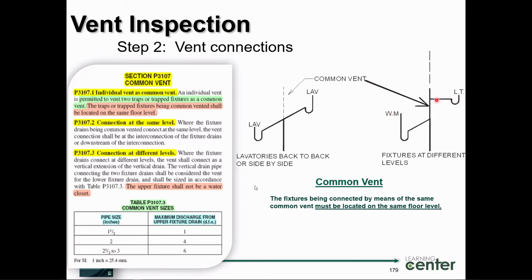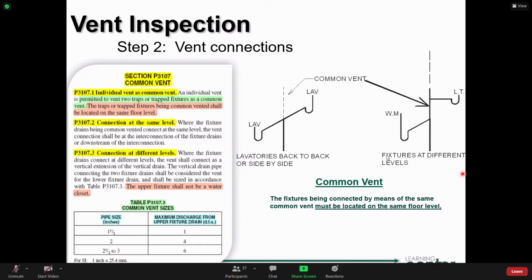When it drains in here, this pipe is going to serve as the vent for the washing machine standpipe and also the drain for the laundry tray. This pipe needs to be a little bit oversized, so I need to apply this table. The drainage fixture unit value for a laundry tub. Anybody know? What's the drainage fixture unit for a laundry tub? It's 2, isn't it? It should be 2.